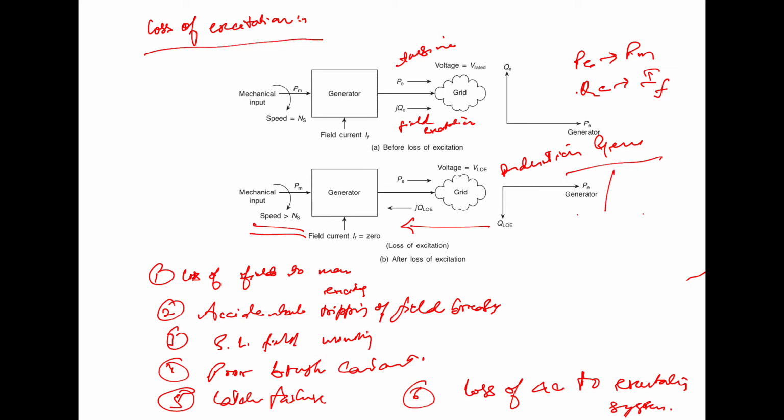So operation as an induction generator necessitates the flow of slip frequency current in the rotor, then current through the damper windings, and slot wedges and surface of the solid rotor body.